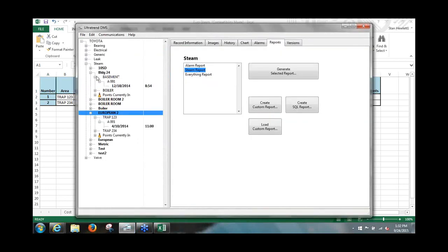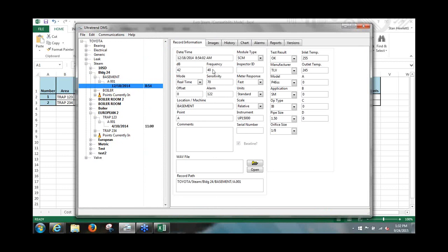This isn't really a true reading that I've actually taken with it. I didn't go out to a basement and actually find some traps. But typically you would have this adjusted to either 20 kilohertz, or 22 or whatever. As long as you're between the 20 and 25 kilohertz range, you're fine. But again, we're not documenting the dB values. All we're doing is listening to the trap and making that judgment call. That's going to be very important with the Ultraprobe.